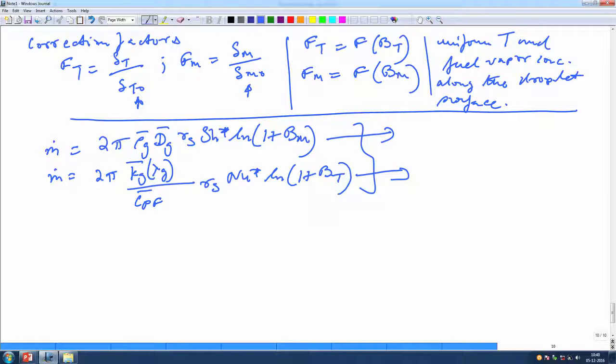So, when can we actually use it? Which one to use depends on which one is a rate limiting step, right. So, actually the smaller of the two is basically what actually governs, okay. That means you can transfer a lot of heat. So, if it is only heat basis, you can evaporate it probably at a faster rate, but it is the mass limitation. That means still this accumulated vapor around the droplet has to be transported out for the next level of evaporation to take place, right. So, it becomes that which one is a rate limiting step over here, and that is important, okay.